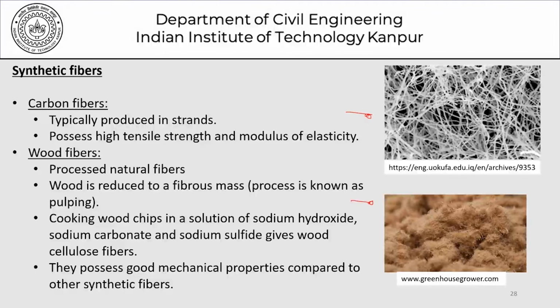I must warn you that when we are choosing to use fibers in concrete, like we talked about the durability in high pH environment, we should also talk about the durability of these fibers themselves due to exposure to water, exposure to oxygen, and so on. Because it should not happen that the concrete initially has a lot of good characteristics, but in 10 years the fibers lose their strength, oxidize or something like that, and then the fiber reinforced concrete has been reduced to simple concrete.